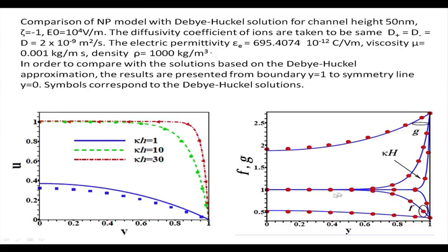So a zero charge density is established in the core. Only a little jump or difference is there near the wall, near the Debye layer. This y equal to 1 is the wall over which the Debye layer forms. Close to the Debye layer you have a large value of G minus F. Outside the Debye layer, you have zero charge density.